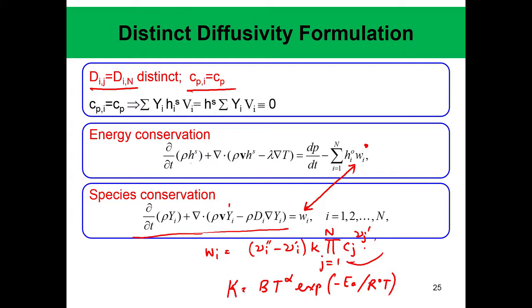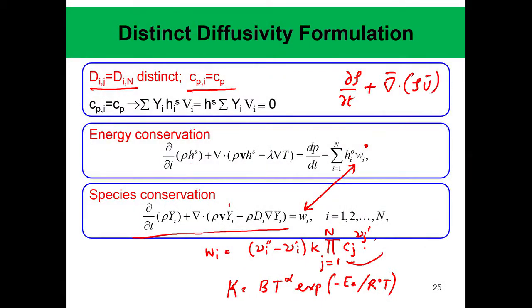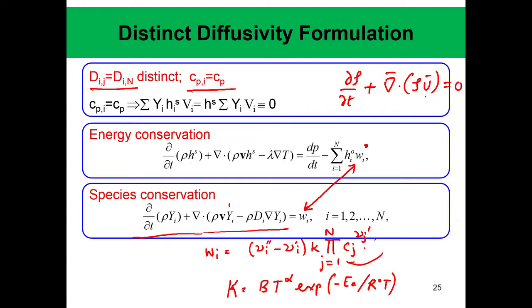This is how the coupling happens, and furthermore when temperature changes, the density also changes, and then you have to consider the continuity equation. Of course, the flow also accelerates when the density changes, because your continuity equation is nothing but d rho dt plus divergence of rho u vector is equal to 0. So, when the density changes, the flow also accelerates, and of course your momentum also changes because rho u is fixed. That is associated with a small change in pressure, but of course we have neglected the pressure here. But this gives you an idea of how the coupling is happening.